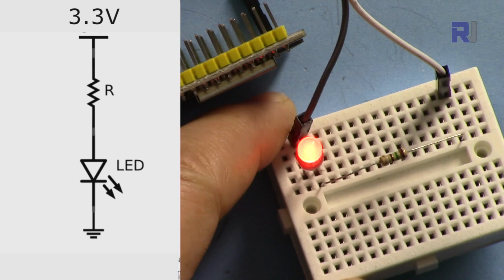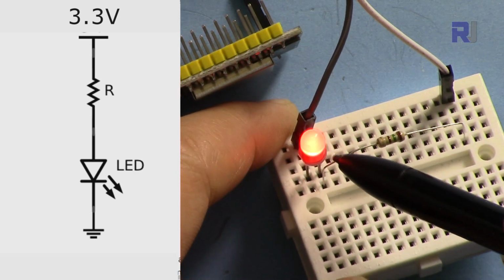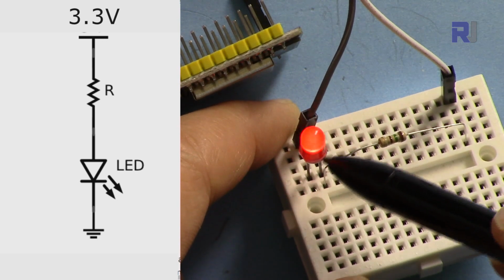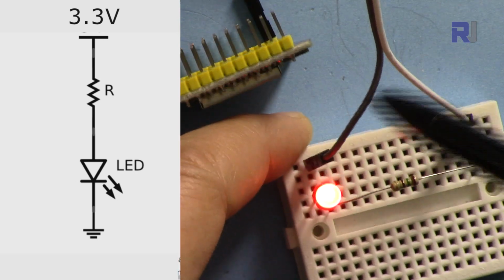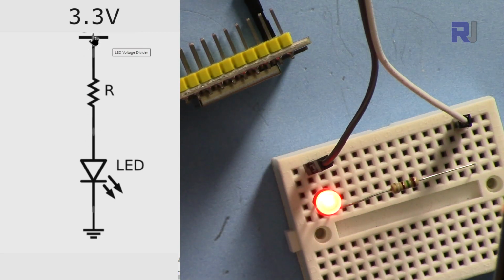Now here this is positive, and it passes through a resistor, goes to the anode of the LED, and from the other side it goes to the ground. This shows 5 volts, but in our case it will be 3.3 volts. We have a resistor, the voltage comes from the pin, which is 3.3 volts. It goes through the resistor and enters the anode of the LED, and the LED will turn on and it goes to the ground. So this LED is on average 2 volts.